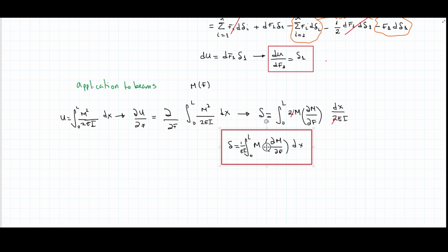So this is very applied to displacement or elasticity analysis, where you are way more interested in how things deform than how they are stressed. But even though you're just looking at deformation at certain points, you are not missing the point on how the stresses are developing there. What else could be said about Castigliano's theorem is that it can solve very complex problems where a multitude of loadings are applied to a body with particular geometries that are not very common. So we could use Castigliano's theorem to determine the displacement of certain parts of the structure.